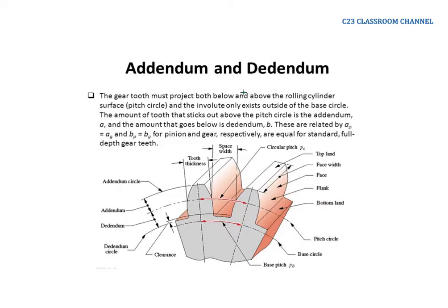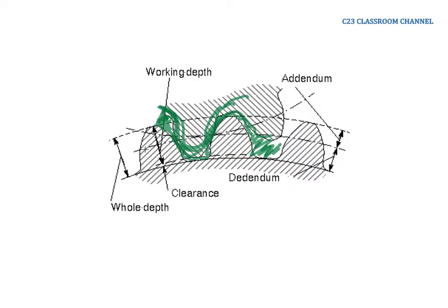So this is the design of the gear tooth. We have the addendum and dedendum. I hope you could understand here. The simple one is this is the dedendum, where the design is still straight like this, and then the addendum starts here, so it starts to have a curve like this. The purpose of this design is to make sure that when these two teeth meet each other, there is no wear and tear at this point, because this point is designed correctly.